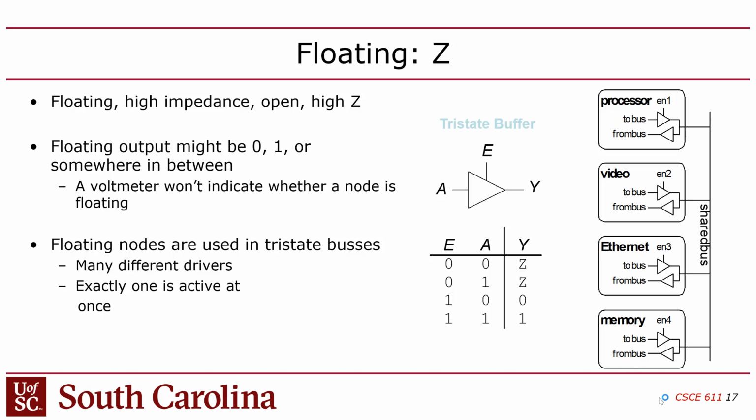Now, just to be clear though, we're designing Verilog to go to hardware. Once the design gets into hardware, there's only a 0 or 1, right? There is no Z and X. Those are only for simulation, for when you're debugging and validating your design. Once it gets to hardware, it's purely digital, right? Now, if you have a contention in a hardware circuit, like I said, the signal may go into the forbidden zone and be undefined. But in general, you think of all digital signals as 0 or 1, okay?